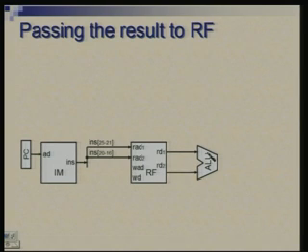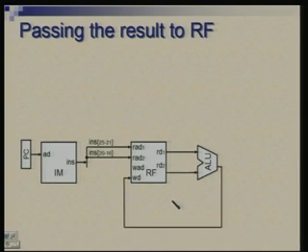So, right now we are not distinguishing between those 5 and just looking at the overall flow of the data. So, output of ALU goes back to this register file to the write port. Okay. Let me just emphasize this terminology. These are called ports for the register file. Okay. Port means, there is something like gateways. So, there are 2 read ports in this and 1 write port, and this is going back to the write